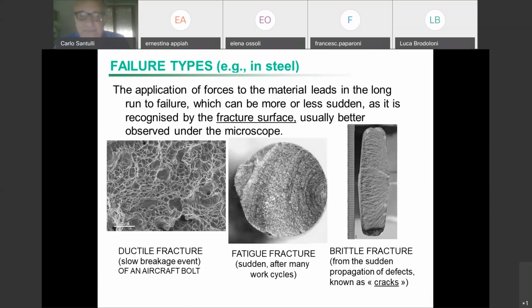If they need 100 bolts to be safe, to carry the load or to join the two parts in a safe way, you put double or triple. So in most cases, you are not very worried about the fact that one bolt is broken.